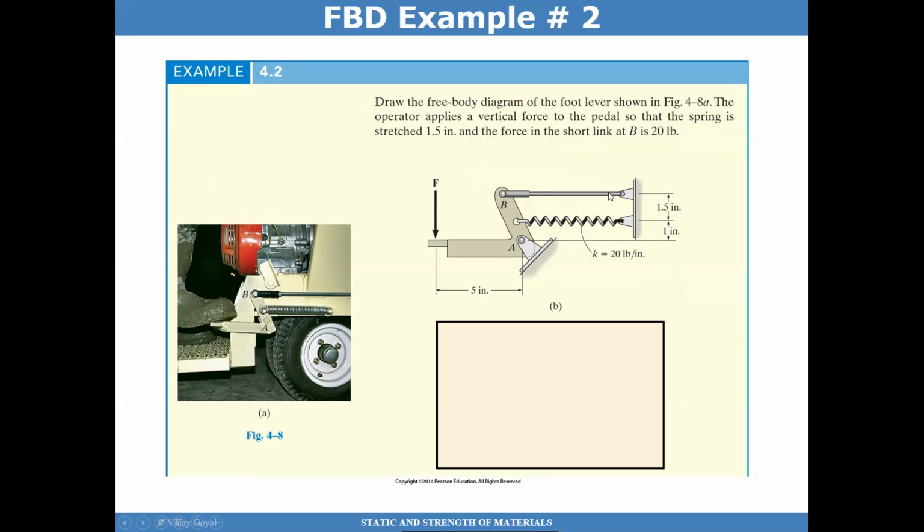The question being asked is, the operator applies a vertical force to this pedal so that this spring here is stretched by 1.5 inches. And then the force in the short link is about 20 pounds. And so the question is, draw a free body diagram of this foot lever.